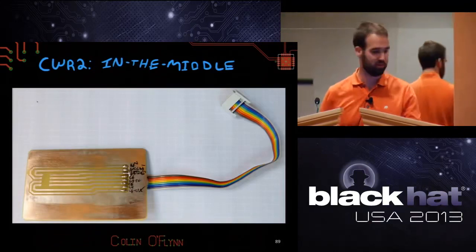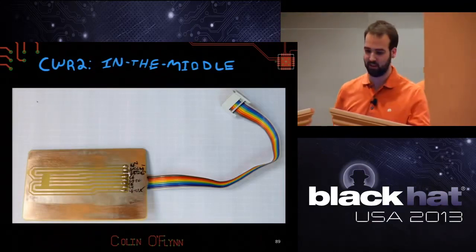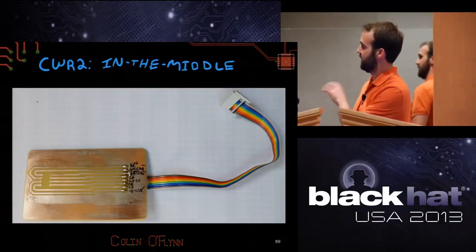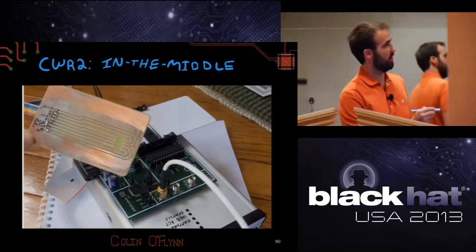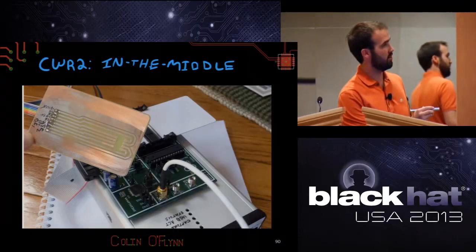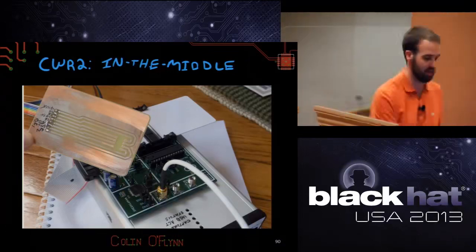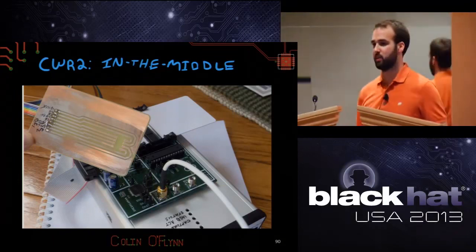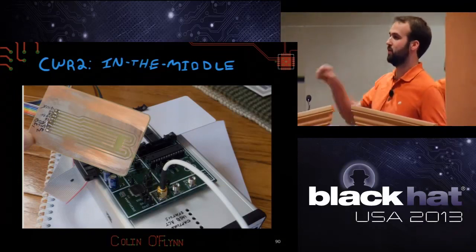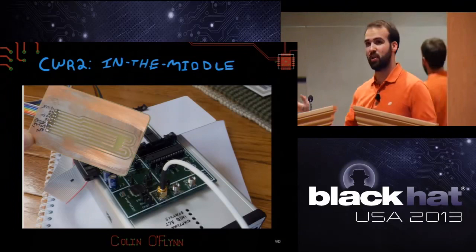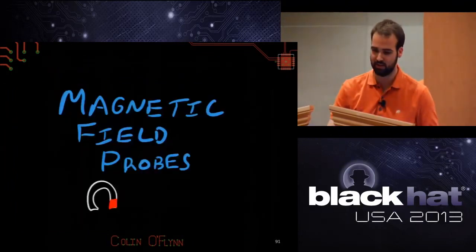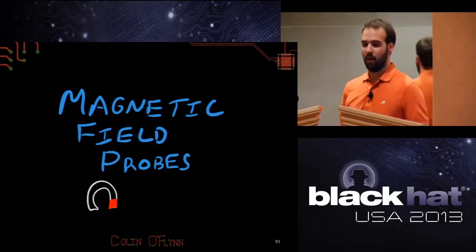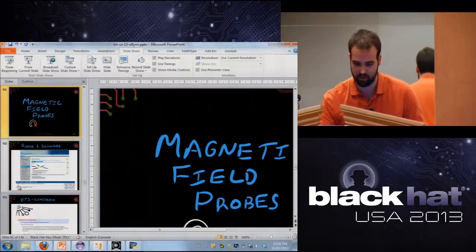And you can also do with the multi-target board what I call an in-the-middle attack. So we have this fake smart card looking PCB. This PCB is plugged into your reader. The other side goes around to the multi-target capture board where you have a smart card inserted into it. And in this way, the signals are going through to the reader while you measure the power, while also monitoring all the signals. And you can do insertions in the data line if you want, or glitches. So let's see if the demo is done running yet.